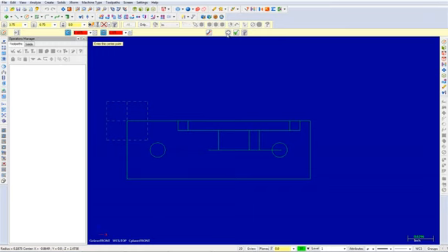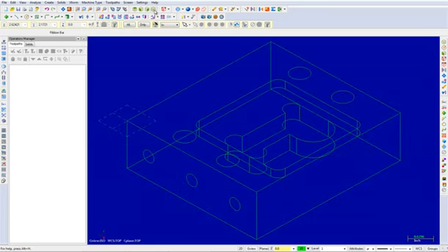For the final time, select the fast point icon. Input the following coordinates: 2.25, -0.75, and press enter. The third arc will appear as shown. You can now select the OK button to exit this command. From here, select the isometric graphics view. Your part will appear as shown.